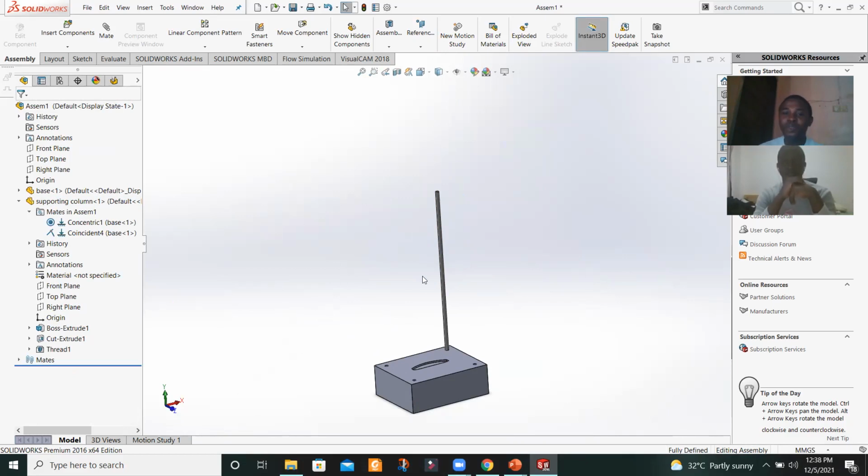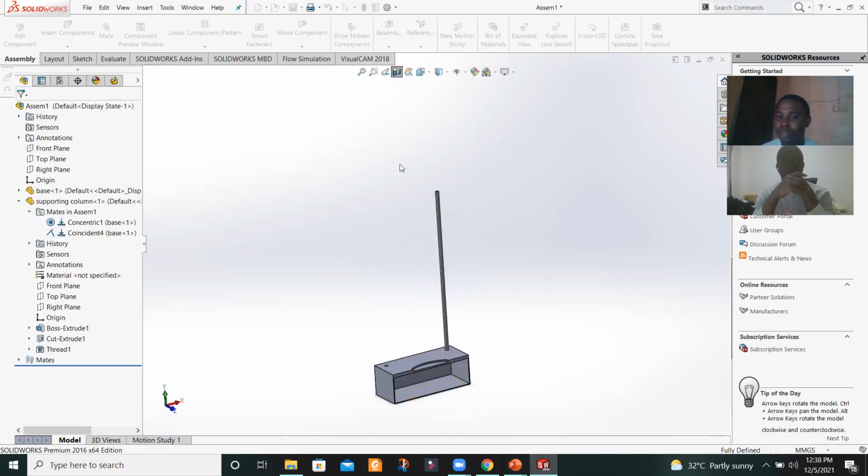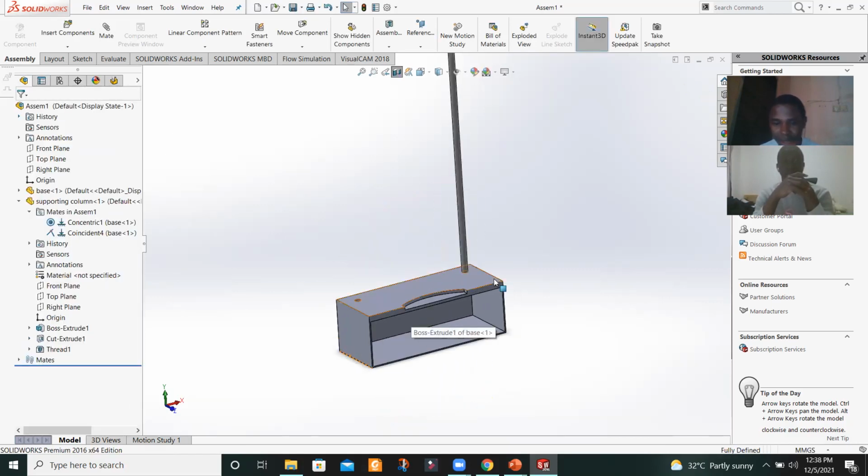This is where copy with mate now comes in. There are standard mates that come with this. Now, with copy with mate, what you do is I'm copying these components and I'm copying the mates that are with it. So you see, it's one of the tricks that make the work faster. But I will do one now. This is not actually the class that I'm supposed to have talked about it. Let's follow the process easily. I just want to stay in a very, very simple way.